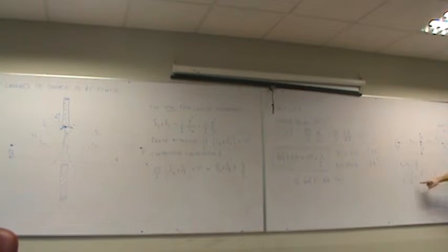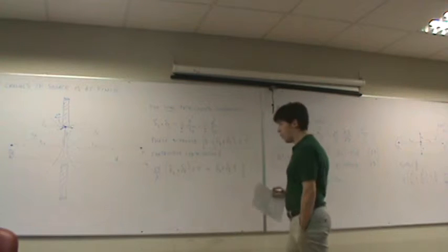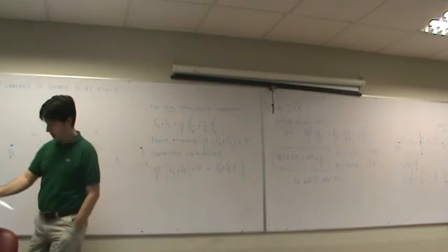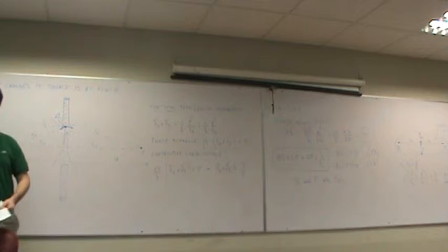And if you replace R1, R2 with D divided by 2, you find rho max, that is also what we call A, equal to the square root of lambda T divided by 2. So this is the maximum size of the first Fresnel ellipsoid. And you should keep this volume free from obstacles if possible.